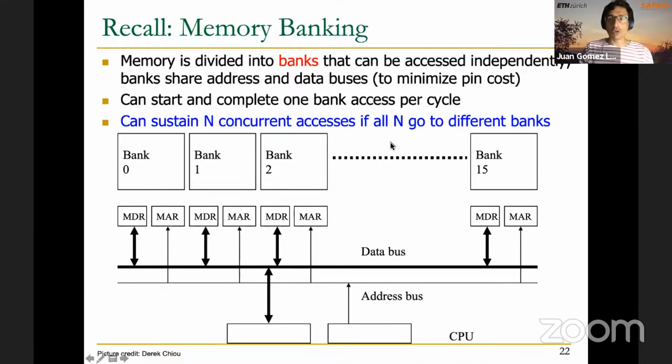So when we talk about banks, what we mean is the different parts that compose the memory. We take the whole memory, we divide it into multiple parts, and this number of parts is the number of banks. So we divide the memory, in this example, into 16 banks. Then what's the port? You can assume that the port is these two registers here plus some add unit that obtains the address that we will access from a base address, the start address, the pointer that points to a matrix A, for example, or array A, and the stride. By using the stride and the base address, we can obtain the specific addresses of the elements of A that we want to access in the different banks, right? So this is one port, this is another port, two different banks, two different ports. Instead, we could have duplicated MDR and duplicated MIR for each bank.